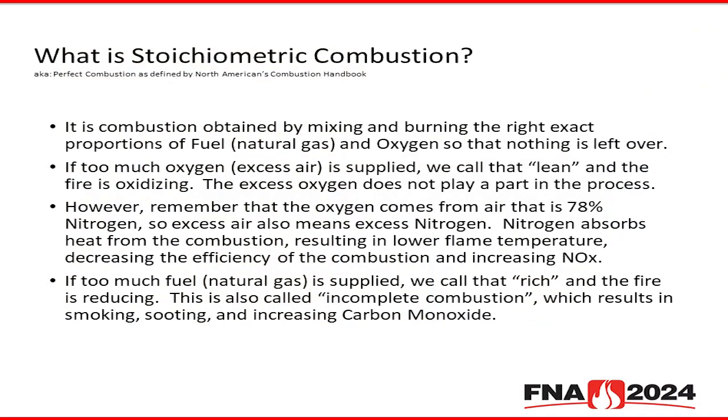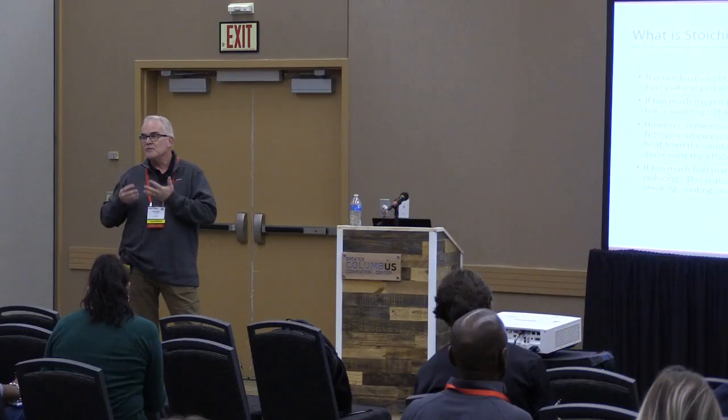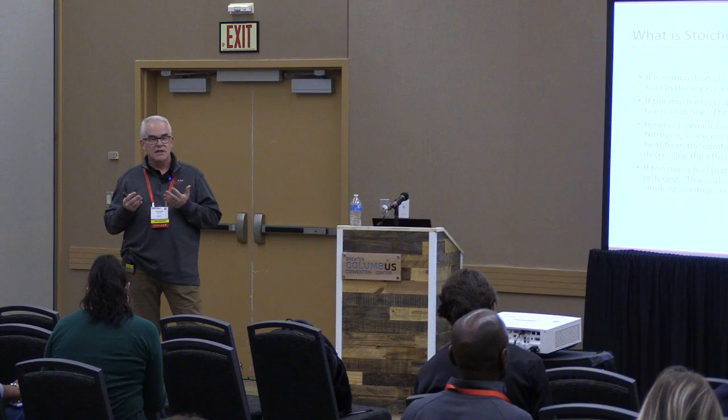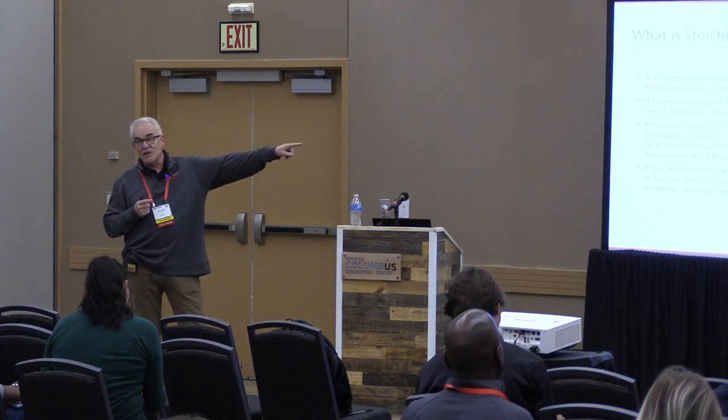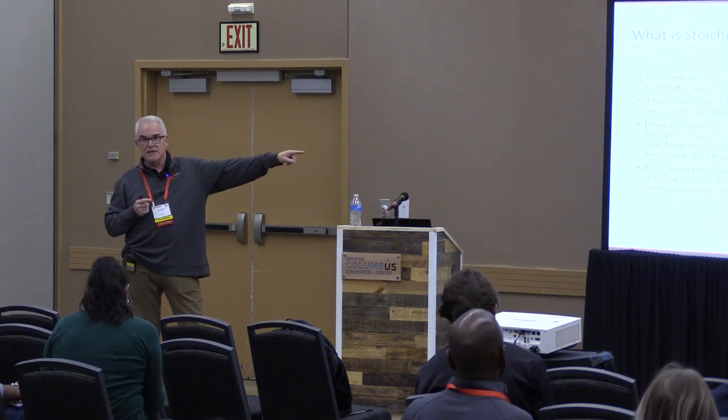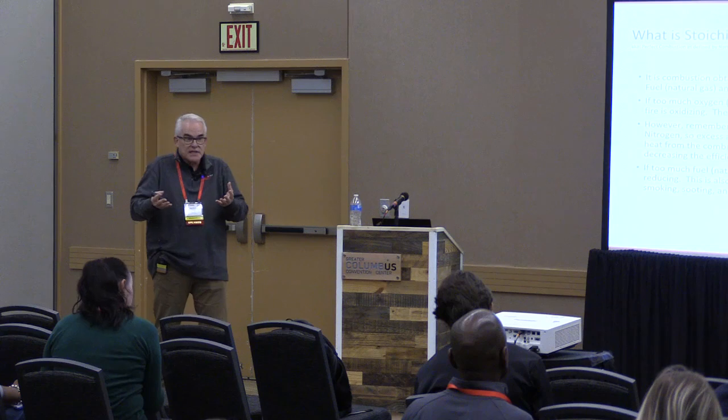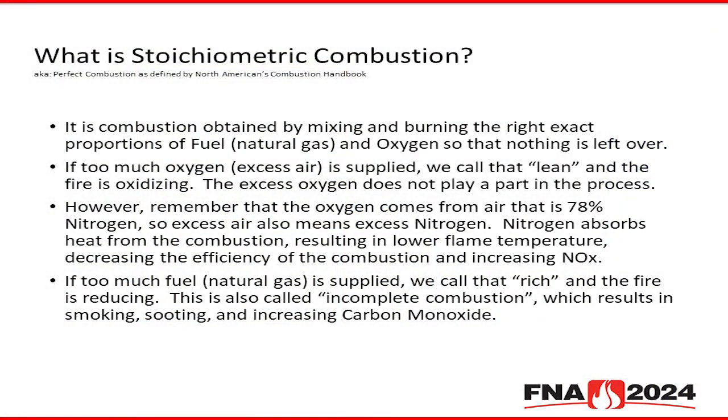The fire is oxidizing. The excess oxygen does not play a part in the process. So you have more air than you need, and the impact of that is now you have a lot more nitrogen than you need, and you're heating up nitrogen because that nitrogen absorbs heat, resulting in a lower flame temperature, decreasing efficiency, and increasing NOx.